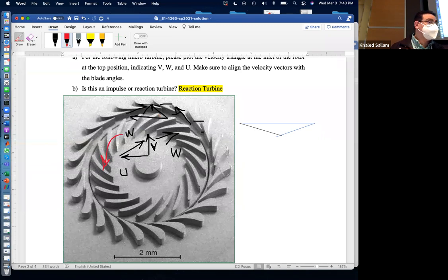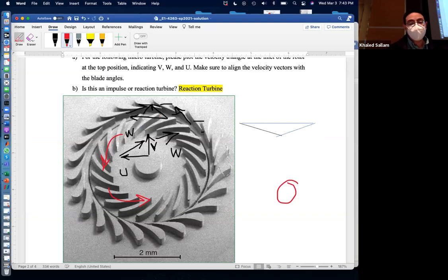The rotor plate in this scenario, it's a compressor, and we are turning counterclockwise. They are bent backward. This is also the same geometry for a centrifugal pump, where they are bent forward, not backward.